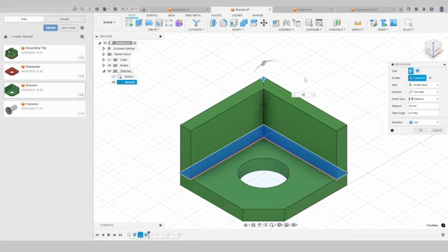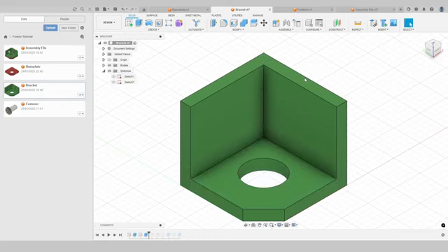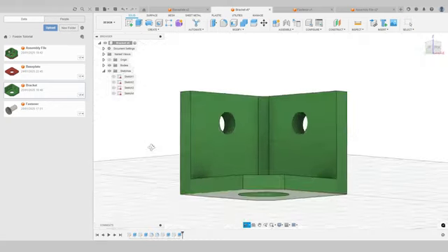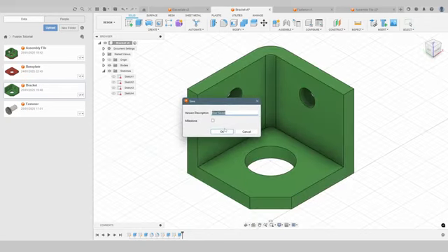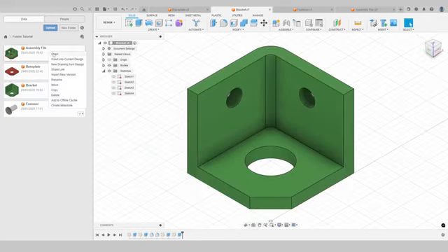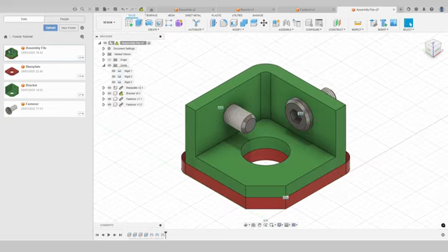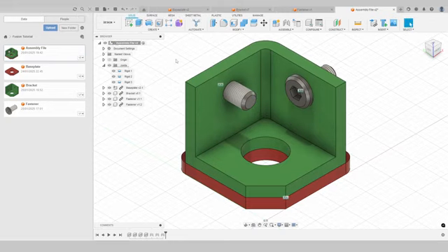So from 40, let's boost that up to 60, press OK. Then we're going to move our arrowhead back to the end. Again, let's save that. Press OK. Let's right click on our assembly file, click open. And then again, we're going to hit the update child component. So it's just going to follow along that update from the bracket, reflect that in the assembly. And there we see now the walls have increased by 20 mil in height, and also the according joints are still relative as well. And so that is an overview of Fusion, or Fusion 360 as it was previously called.